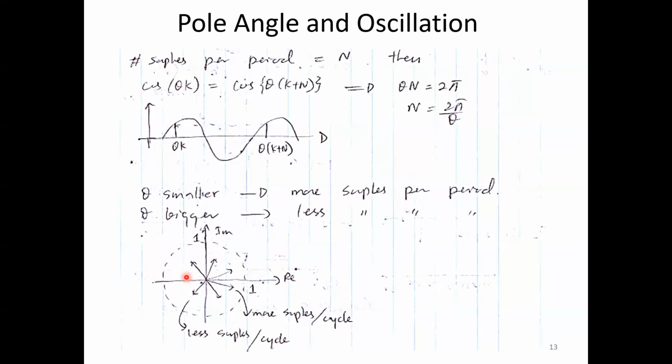So by the time you take the next sample, by what angle has the waveform changed? If it is too much, if it is like 70, 80 degrees, right, maybe you are marginally okay. But if it is 120, 130, 180 degrees, it is simply useless information you are taking, right?